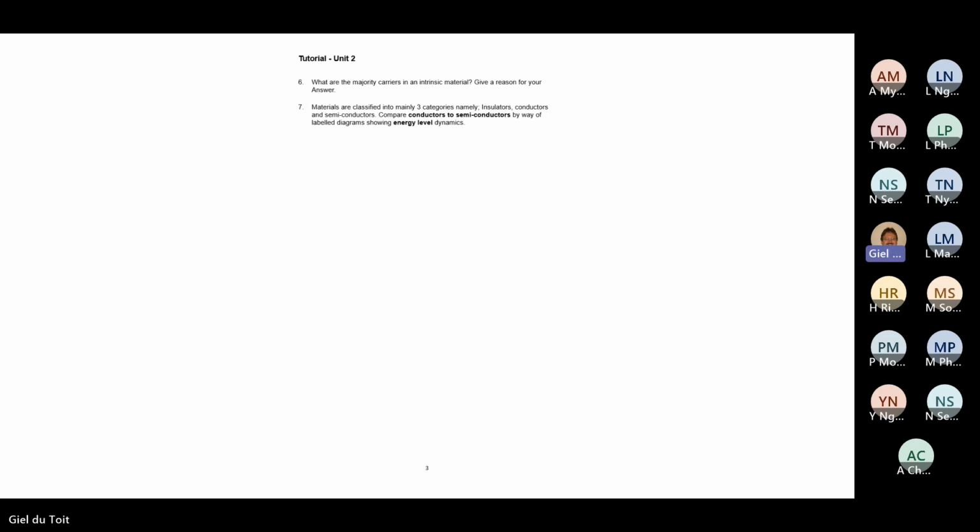We also call them holes. Holes and electrons. So all the electrons ran away from here and they go and sit on this side. It's like a capacitor, guys, where you charge a capacitor, all the positive ions sit here and the negative electrons go and collect on this side. And therefore, the majority carriers here are electrons, the majority carriers here are holes. You got it.